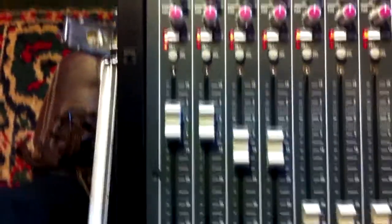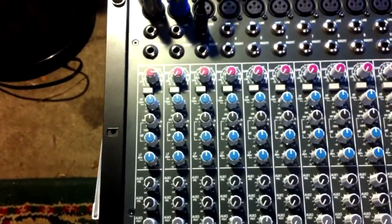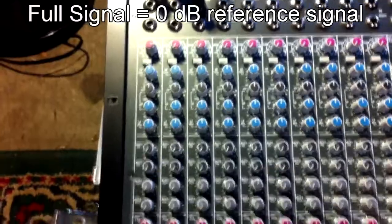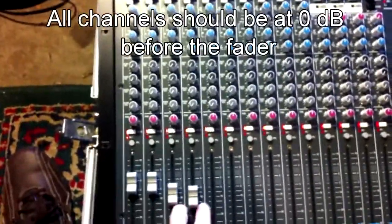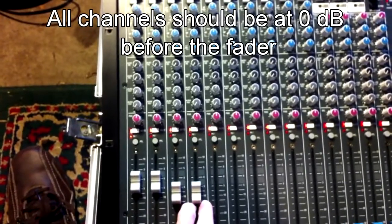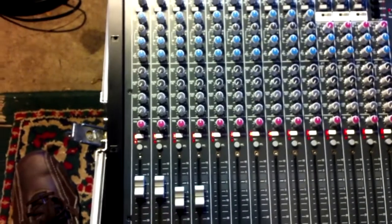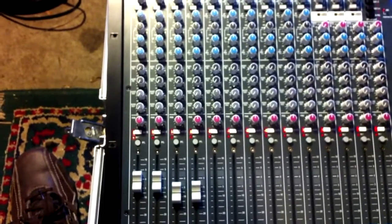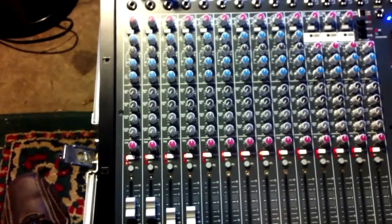The preamp is what you use to make sure that the signal coming in is strong enough before it hits any of the other circuitry. So ideally, if we're using a big number of channels, each channel should actually be at the same volume by the time it reaches the fader. The thing is, different microphones, different instruments, different components that get plugged into the mixer all run at different levels. So we use the preamp to balance this out.